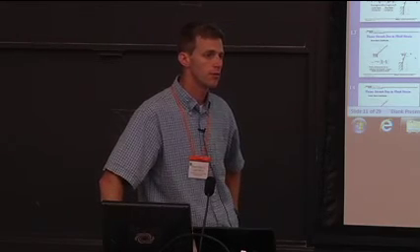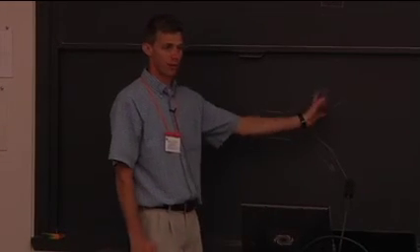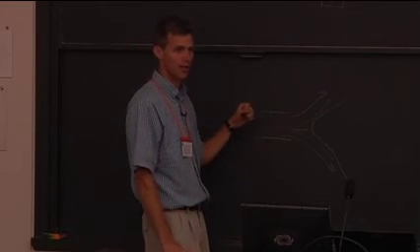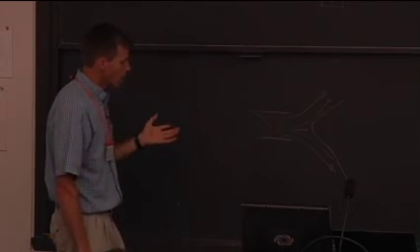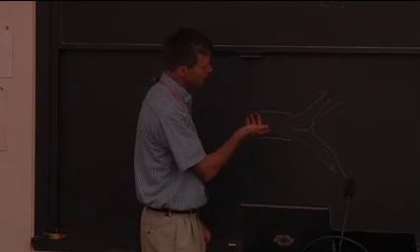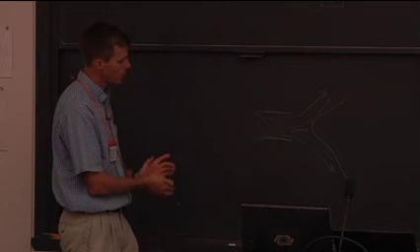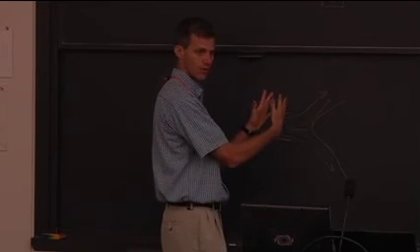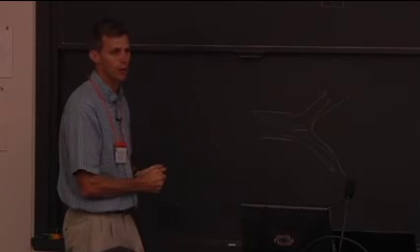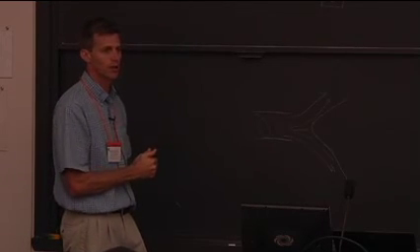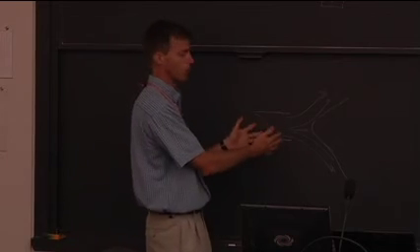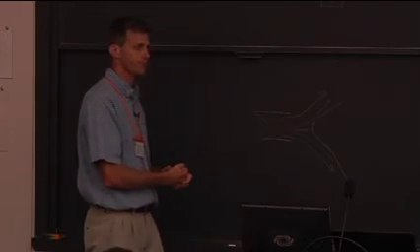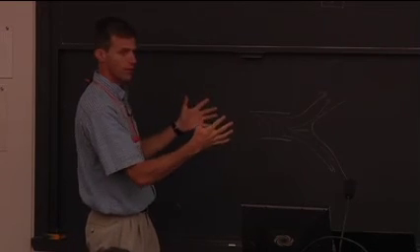Because you can fluctuate. That's right. So I will tell you that most gas turbine companies I've talked with have a hardwired nervousness about flames stabilized out in free space. They want a piece of metal for it to hang on to. The question is whether you can design this device such that it has enough turndown and stable range. Frankly, that's so geometry specific and fuel specific, I wouldn't want to make a general conclusion about it. But there certainly is an operational window where you can find a stable flame.